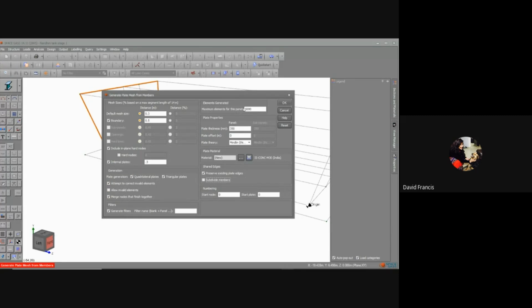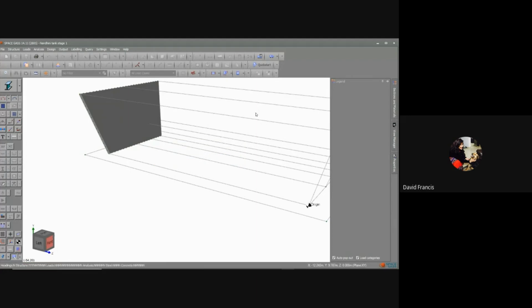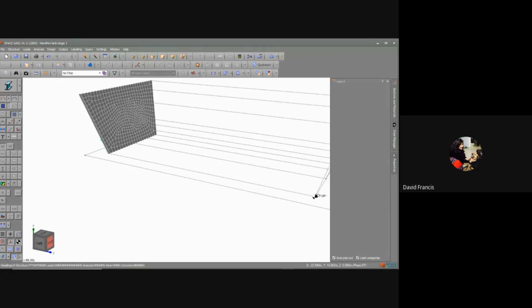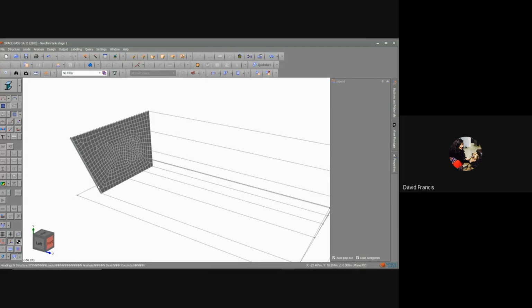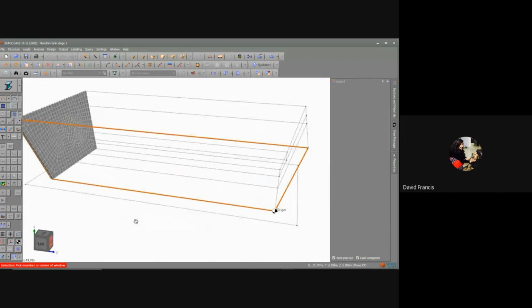It may tell me that there are more than 5,000 elements. It might tell me that they are nonlinear, but no, it's done it. Now the meshing has been generated, and I just want to turn the meshing on. So we have edges for both plates and for members to make them look better. So you can see what it's done. Now I can carry on, because if I want this face done, I didn't break up the member on the left there, so it makes it very easy for me to come here and do this.